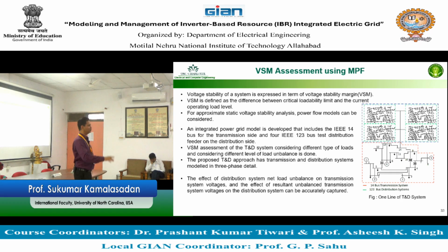These TSA tools are actually running differential equations, but you are also integrating algebraic equations together to form a differential algebraic equation model. We have something called long-term, short-term stability. For that, the angle you will be seeing in an electromechanical time frame.